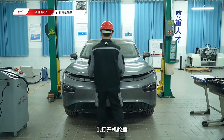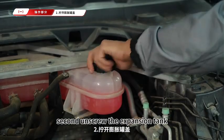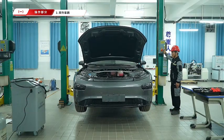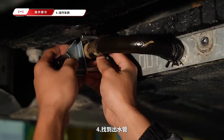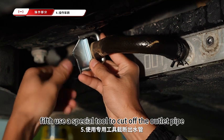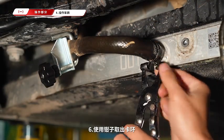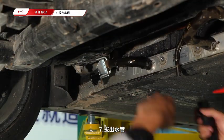First, open the hood. Second, unscrew the expansion tank. Third, lift the vehicle. Fourth, find the outlet pipe. Fifth, use a special tool to cut off the outlet pipe. Sixth, use pliers to remove the retaining ring. Seventh, pull out the water pipe.